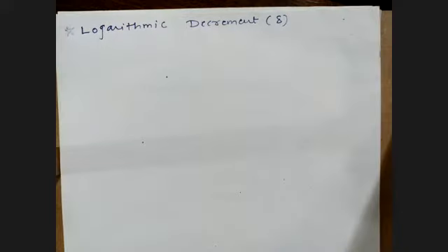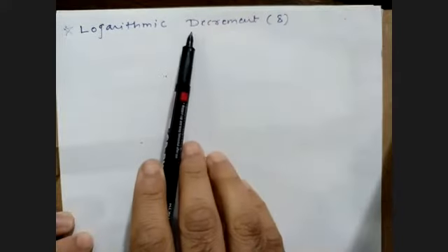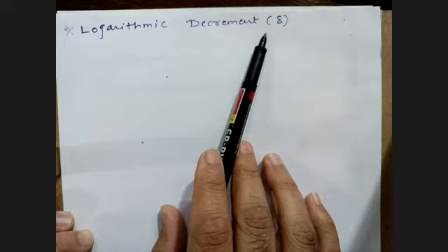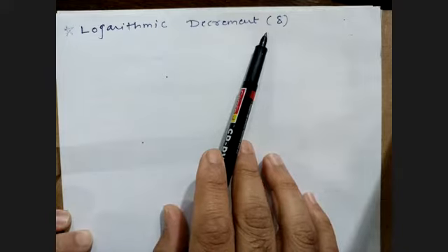It is called delta. This is a new topic of this chapter on damped vibration. What is logarithmic decrement? Besides the word decrement, it is related to the amount by which the amplitude has been reduced, and at what rate. That is nothing but your logarithmic decrement.